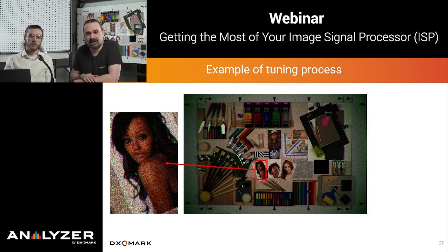So 20 lux is not very much light, so you have some noise from the capture itself. And then we applied an ISO speed, we applied a gain, we multiplied the noise the first time. Then we also applied the white balance scales, which means that two of the channels have been multiplied by something larger than one, and on these two channels you increase the noise even more. So in the end, without denoising, the image is not really exploitable.